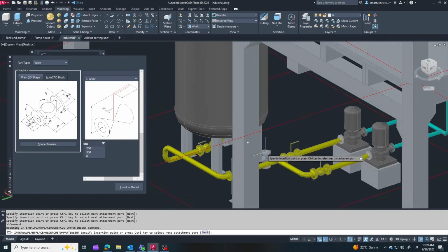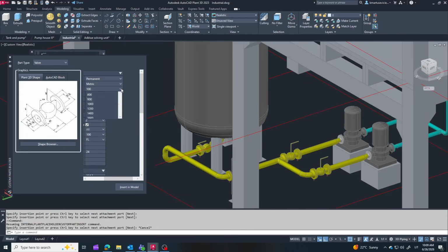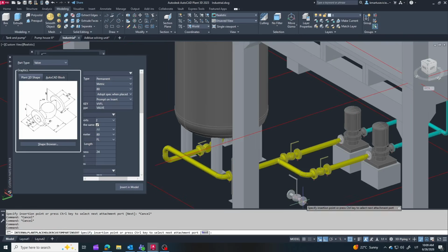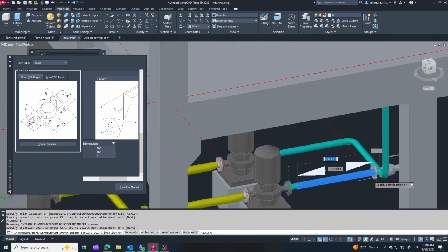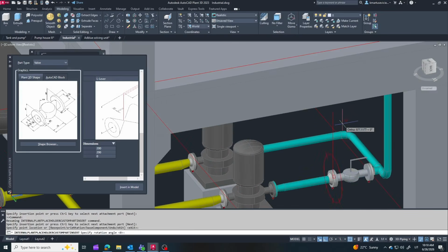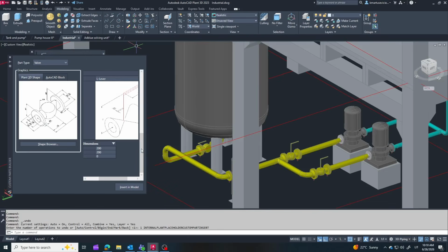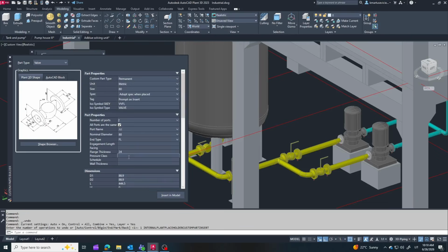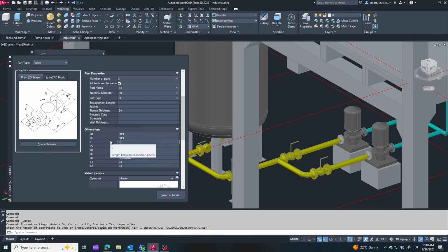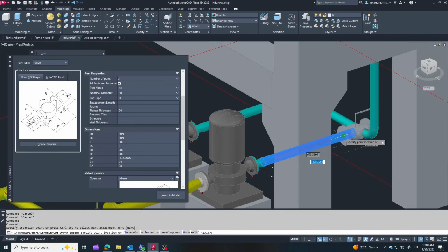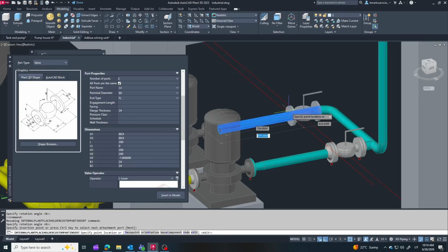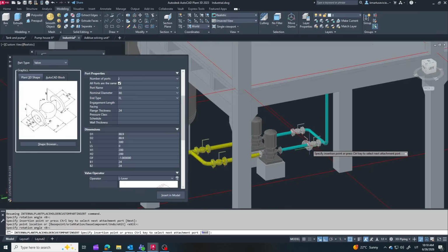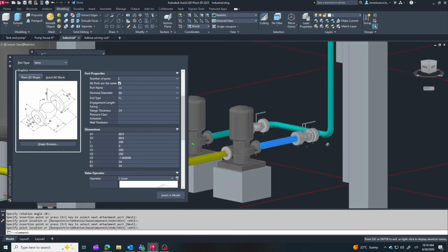In this tutorial, I'm using only manual valves, but many industrial valves are automated. The most common actuator types are pneumatic and electric. Pneumatic actuators use compressed air to open or close the valve. They are fast, reliable, and very common in process plants because compressed air is usually available throughout the facility. Electric actuators use an electric motor and gearbox. They don't require compressed air and are often used for remote operation or where slower, more precise movement is acceptable.